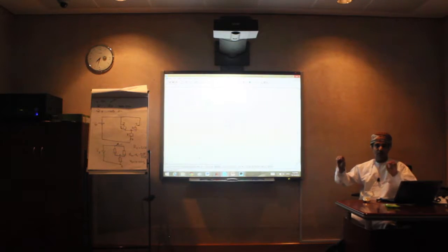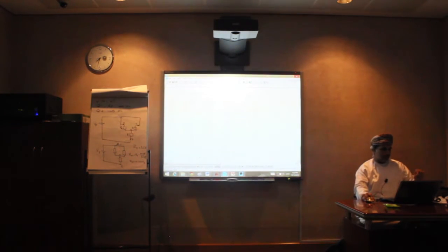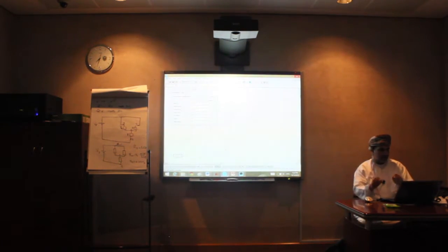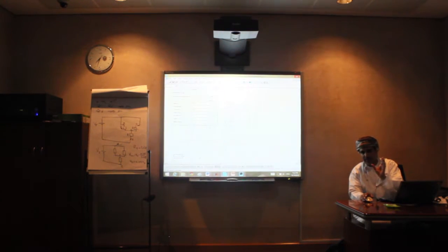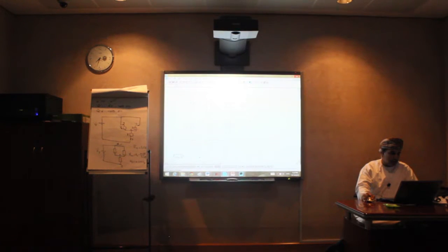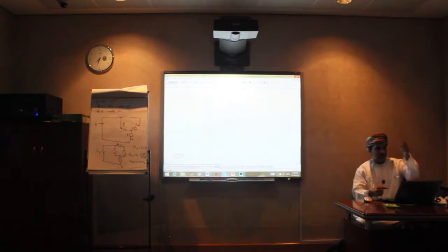I'm trying to do what we explained now. For example, for the first switch, which is this one, I will turn it on for a while, and keep it on with a duty cycle of 0.5. So that means I have 50 hertz and I keep it on for the first half cycle, right? And then turn it off, and the opposite for this one. So I'm using here the NOT gate. You see that NOT gate? If this one is on, this one should be off. And the same thing, I will shift these two by 120. I will turn on this one and close that one with the NOT gate. If this one is on, the other one is off. You see? That's why I'm using this NOT gate.